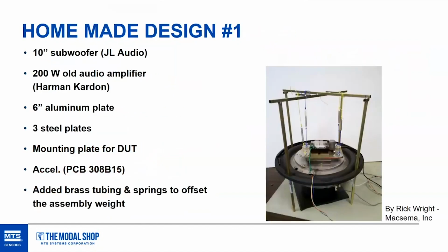So a shaker works pretty much like a loudspeaker, and in that way we've seen many people attempting some homemade designs where they were starting from an existing speaker and trying to shake something. The challenge here, and I don't recommend you do this at home, is that speakers are designed to produce sound waves. So you're trying to pump air, and when you're doing vibration testing, you're typically interested in optimizing the force output of your shaker.